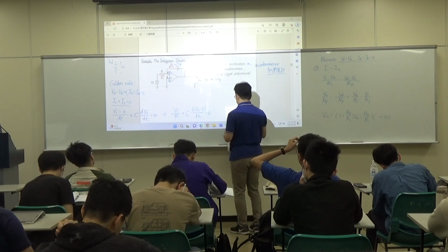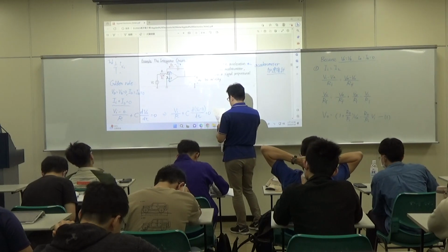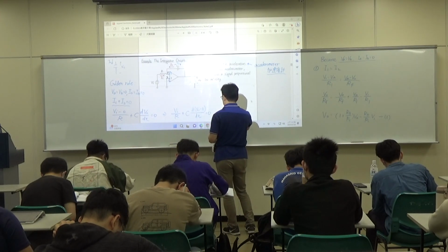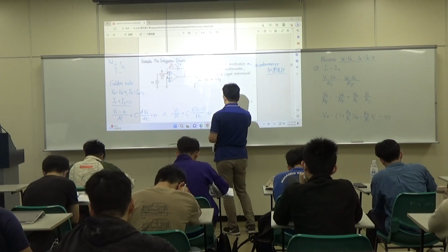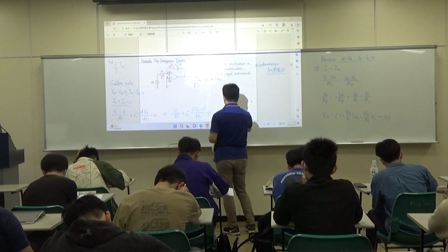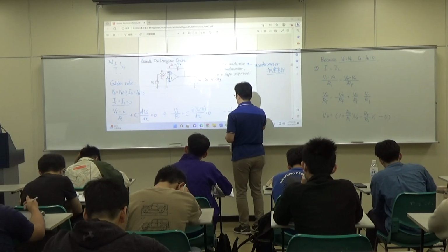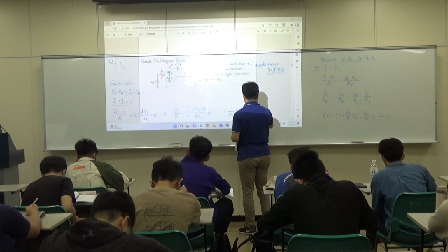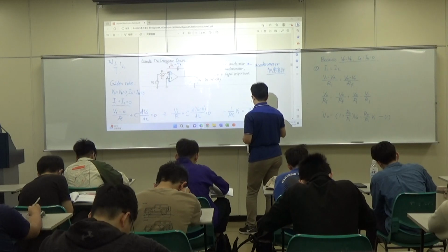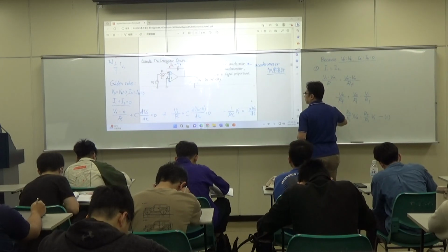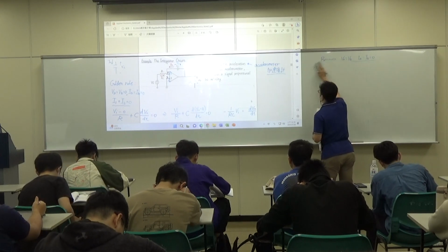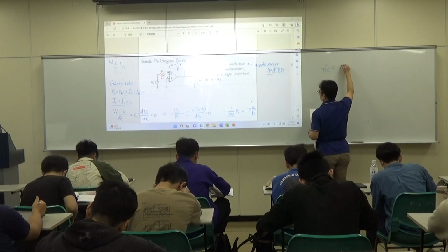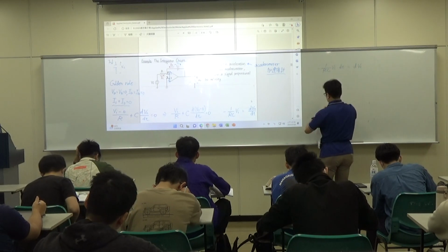We rearrange it a little bit. So let me rewrite. We have minus 1 over RC times VI equals dVO dt. We rearrange this so that 1 over RC VI dt equals dVO.